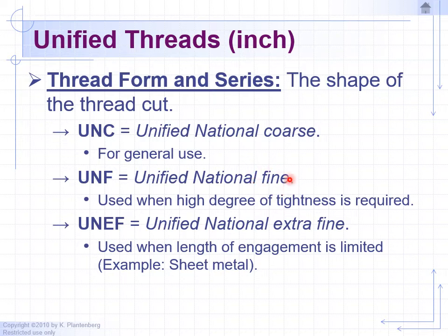Also inside of a combustion engine, where you have rapid movement, the parts inside with threads will have fine threads, tighter together. Now things like water pumps, where you attach it to the engine block, or where you attach the alternator to a bracket, those will have coarse threads where there's no rapid movement, like high RPM, like on the wheel studs. Then you'll just use a coarse thread.